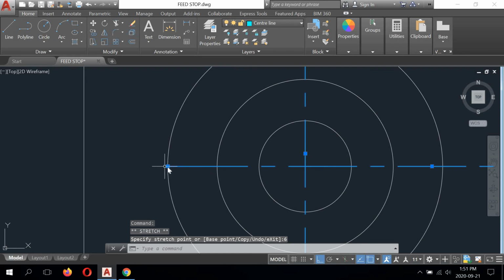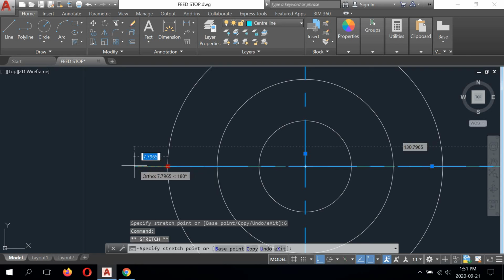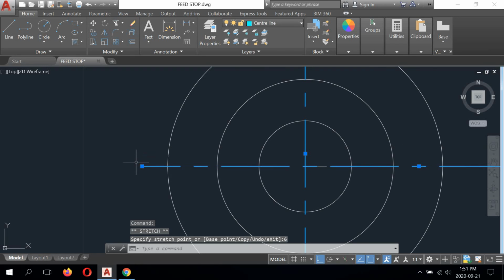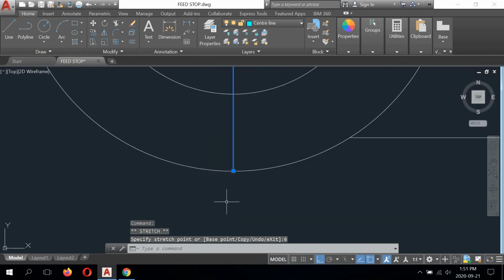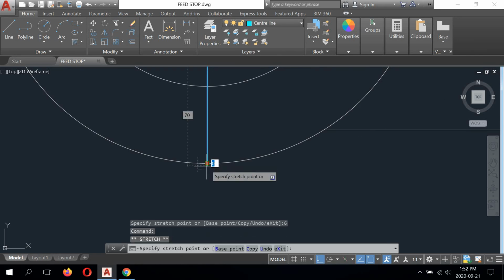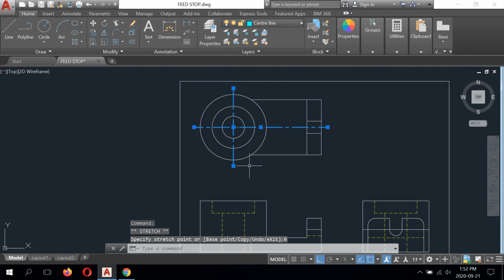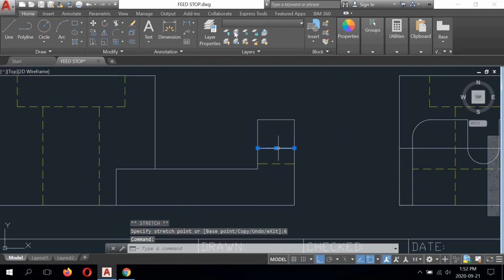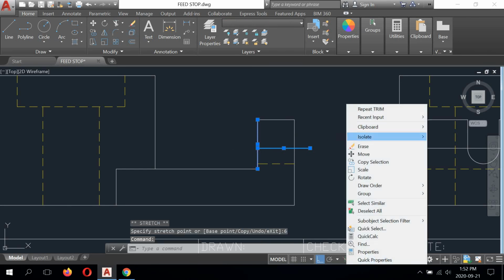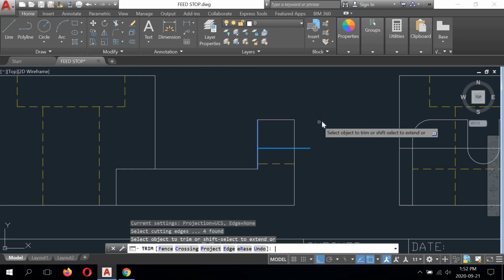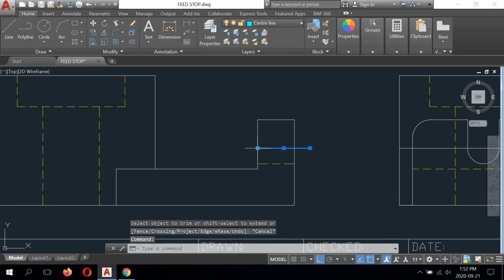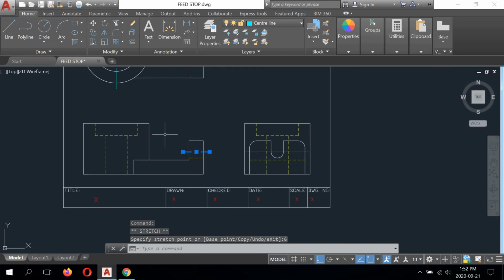So if you do a conversion from imperial to millimeters from 1/4 inch, you get 6.35 millimeters. And the reason we go with 6 millimeters is because it's easier to remember, right? We just round down to the nearest whole number. So it's better to say 6 instead of 6.35. This line here also becomes a center line, and it gets gripped out 6 millimeters per side. I just selected the wrong line. Okay, so we've got that one done.